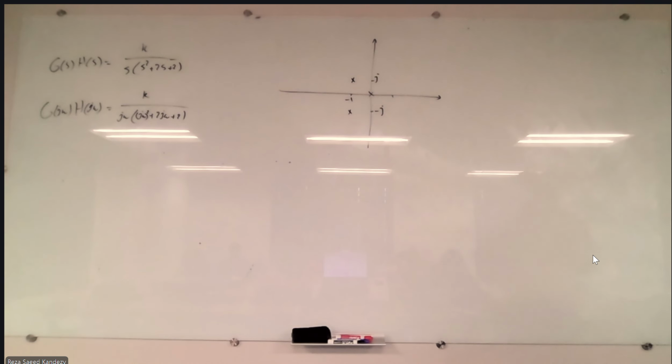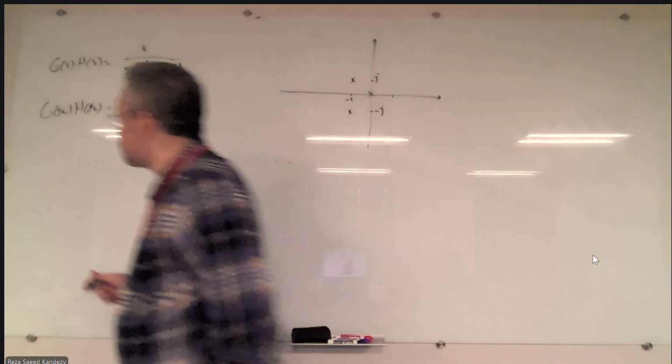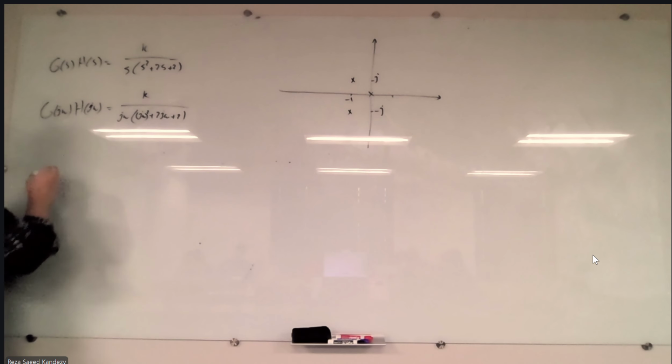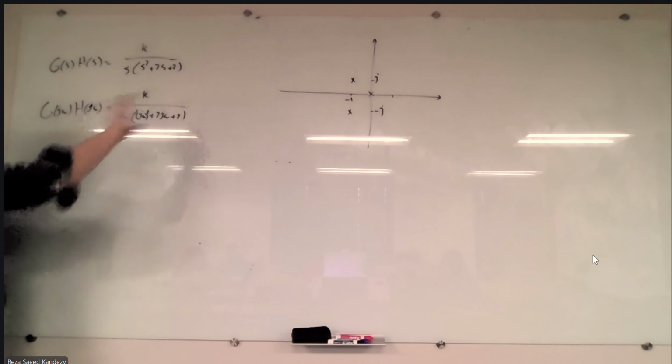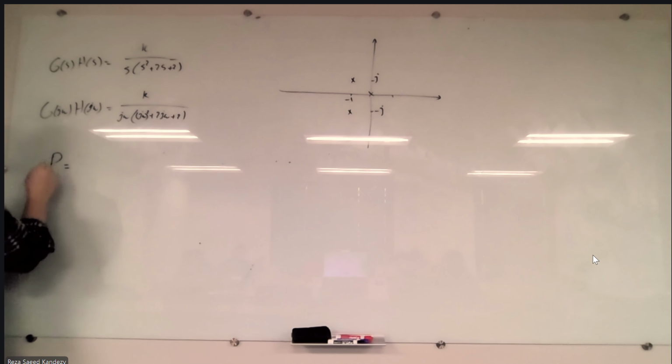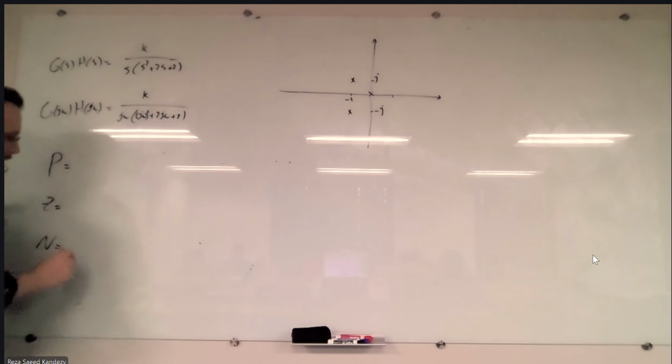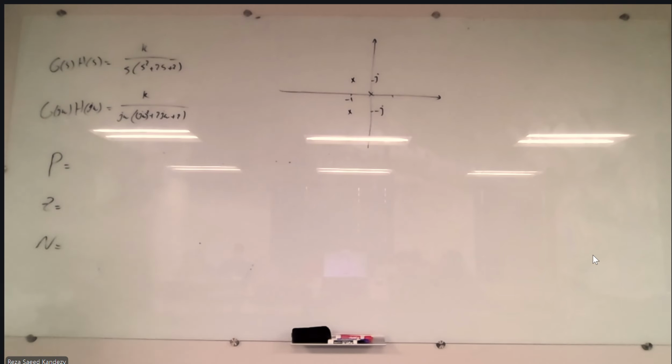Now, for stability analysis based on the Nyquist, we needed 3 numbers. One was the poles on the right hand side, another one was the zeros on the right hand side, and then how many net clockwise rotations we are going to end up with in our function domain, in our mapped Nyquist, around point -1. Are you good?